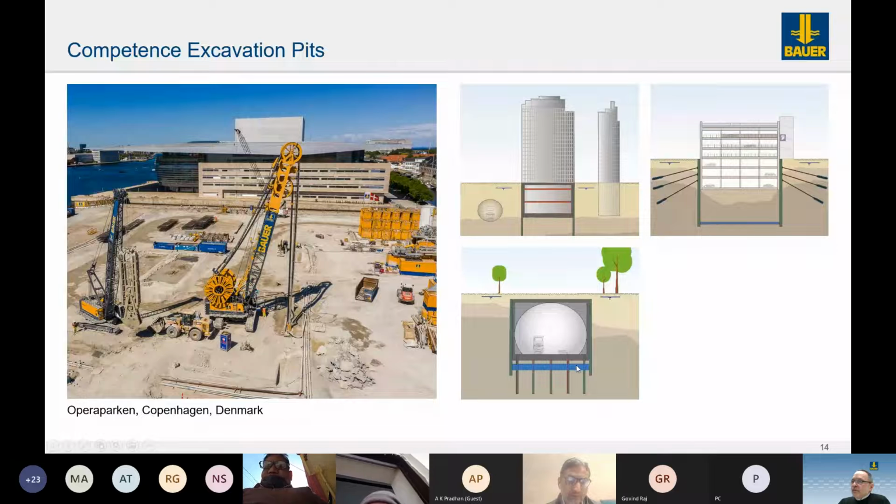Then also if you have tunnels or very deep basements, depending on the geology and the water table, you need to make a slab underneath, a grouted slab, for example. And depending on the depth of the slab, if you have a high slab, you may need to add piles to prevent an uplift of such a slab when you're excavating your excavation pit.